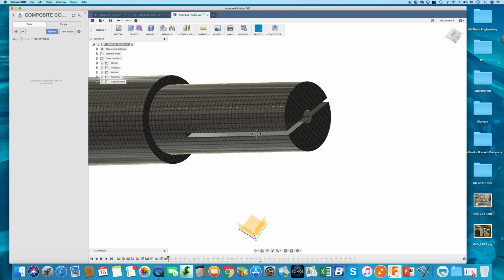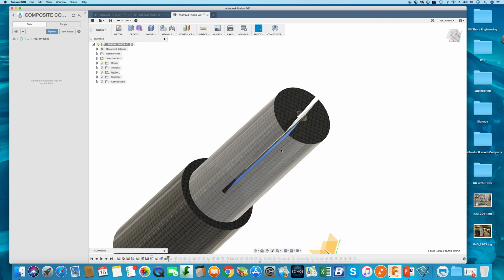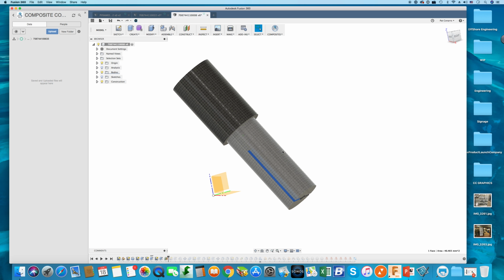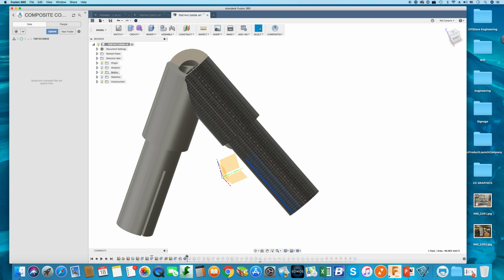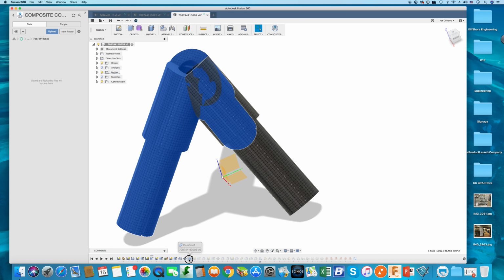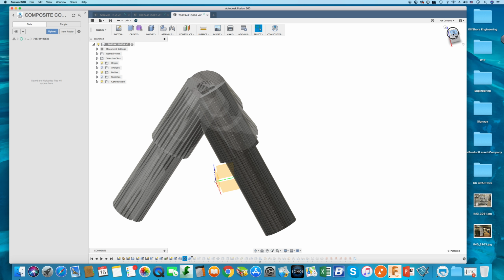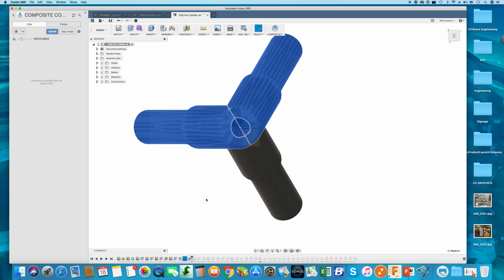So this is, I think, a 0.5 millimeter split here. We're going to 3D print this, so don't worry about manufacturing, and we don't need any draft on anything. And so we come through and we create this. We join everything together. So this is the join command. So we rotate a pattern, and so now we've got a connector that's got the right angle.